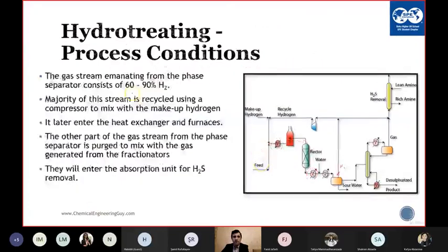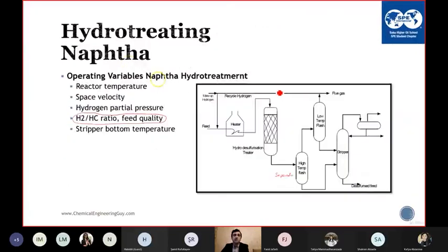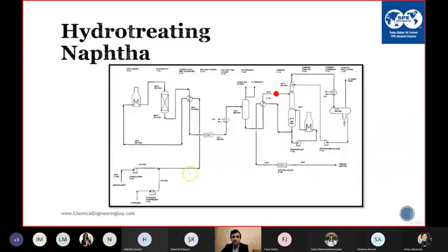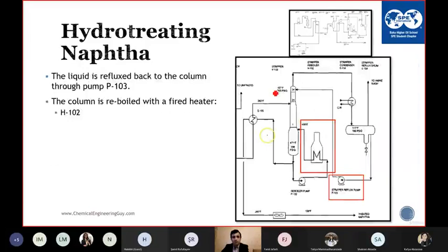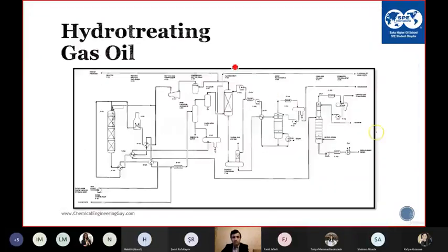For instance, now we have the modernization project in the Howard refinery, the hydraulic oil refinery. The diesel hydrotreating unit is the main unit of the project. It produces Euro 5 diesel. Euro 5 diesel means that you have a maximum of 10 ppm sulfur in the diesel. This is the PFD, the process flow diagram of the process. I will talk about it in detail.